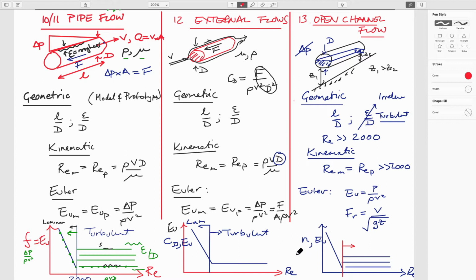And we'll talk about a thing called a Manning coefficient, which is really a drag frictional factor, which accounts for friction on the side of the flow, the wetted perimeter of the channel. And again, there's a laminar portion and a turbulent portion. And the reality is that since we know that the Reynolds number is a density, a velocity, and a characteristic dimension, and a viscosity, that characteristic dimension for a channel is pretty big compared to a pipe, which might be centimeter scale. An inch pipe in a house is 2 centimeters.